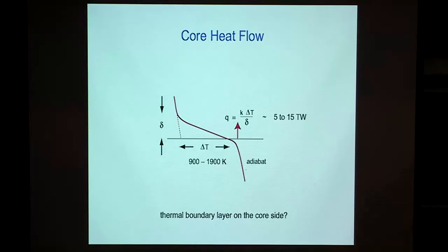Yeah, Michael. Mark asked whether it's the difference in thermal conductivity that gives rise to the differences in the two delta T's for the boundary layers. And it's the difference in viscosity. It's really the difference in viscosity that plays a huge role.